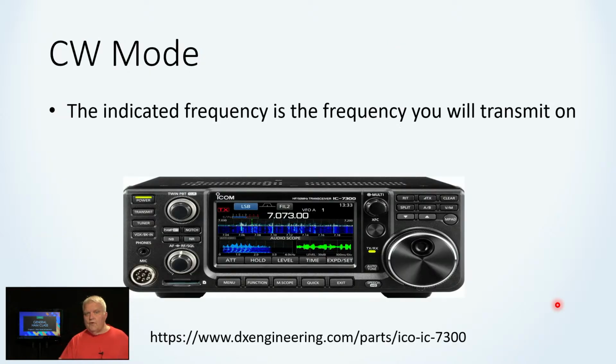So Morse code. Okay, I got my radio now set in the CW mode. Here I am on 7073. That might not say CW, but assuming that it does. With CW, the indicated frequency is the frequency that you will transmit on. And you think, okay, great, so I'm only going to transmit on one frequency. No,